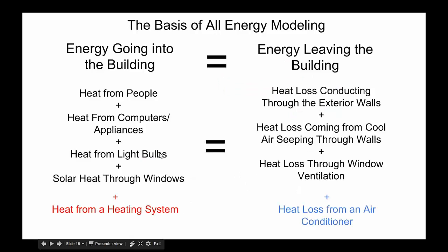And just so you know, the way that the energy modeling software we're using does this dynamic calculation, because I've explained roughly what steady state is, and this is a slide from the previous time, is that it's doing a calculation where the energy that goes into the building has to equal the energy that leaves the building. So that's the first law of thermodynamics. Energy is never created or destroyed. And what EnergyPlus does is run that calculation every single 15 minutes of the year. And that's what allows us to get a very dynamic picture of how our building works over the whole year.